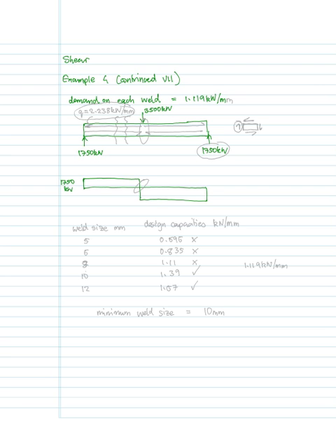Well, if we did a free body diagram of the web, just the web, so not the weld, let's just sketch that as a traction Q, and that value Q is going to be equal to 2.238 kilonewtons, to be shared between how many webs there are.